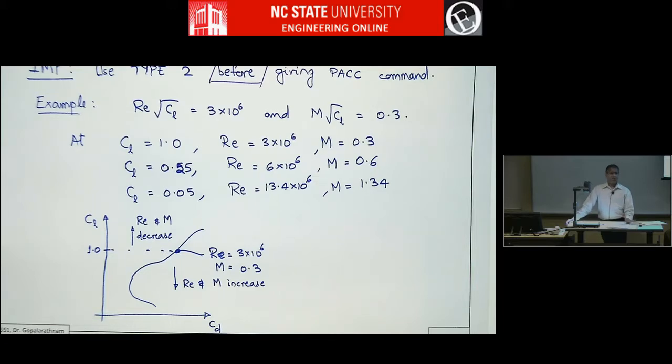Yeah, negative angle of attack is not necessarily bad. You can have an airplane at a slightly negative angle of attack. If you have a highly cambered airfoil, you can fly at a slightly negative angle of attack in very fast cruise. That's okay, like -1 or something. That is not too bad, but CL of 0.05 is almost like a dive. It's so fast that it's probably not in level flight. So if an airplane is in a dive, it will be at a very low CL or even CL of 0. So that RE times square root of CL expression is no longer correct, right?